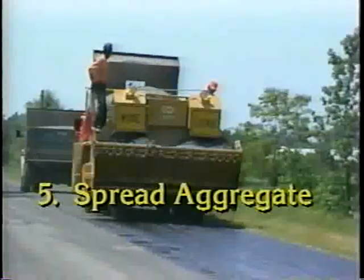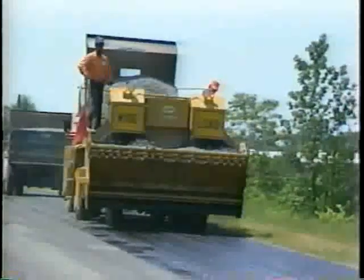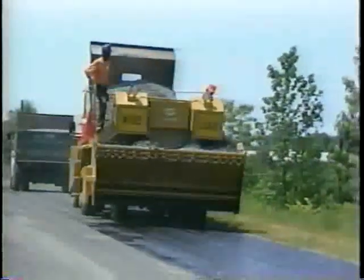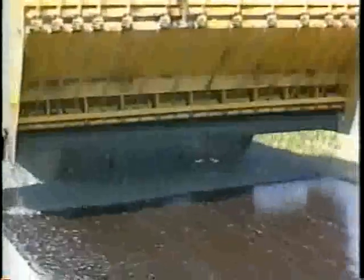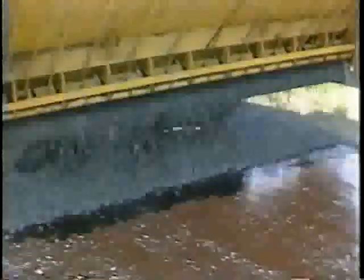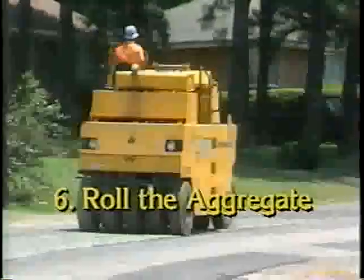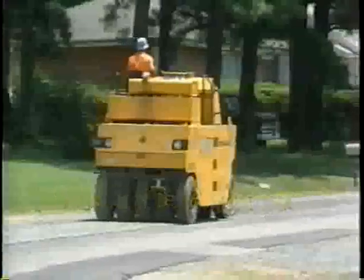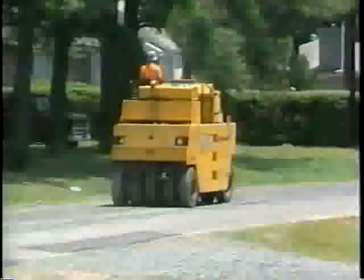Step 5. Spread aggregate. Spread the aggregate immediately after the asphalt is sprayed. When using emulsified asphalt, spread the aggregate before the emulsion breaks. Aggregate must be clean so that a good bond can form between it and the asphalt. Step 6. Roll the aggregate. Roll the aggregate immediately after the aggregate is spread.